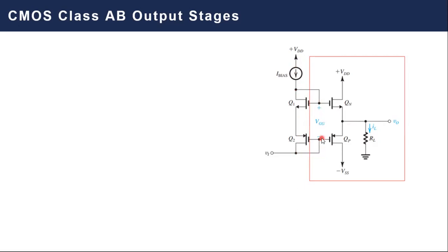And this is a very common configuration in a MOSFET when you would like to force your MOSFET to work in the saturation region. Again, please revisit the electronics lecture in order to remember this saturation and triode configuration. So when VDS is greater than VGS minus V threshold, it is saturation, which is the case here because VDS and VGS are equal by this short circuit. So simply, you create your VGG now using this schematic or this branch.